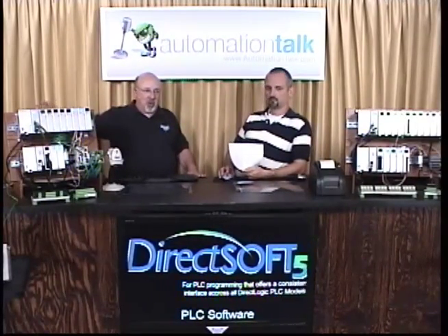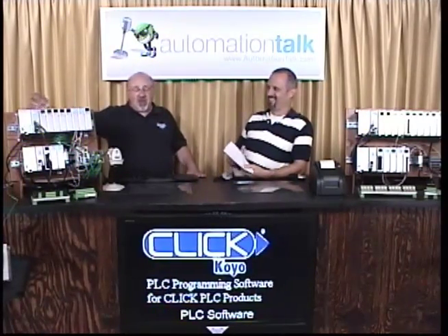We'll sit down. I just know that after the show, we always have some customers who are asking, I like that example, or I want to play with that example, or I want to see that example. But I should mention real quick, if you want to play with the example of using a GS drive to produce heat through light bulbs, it's not really a good application because a light bulb, when it's cold, has a very low resistance. So I have to tether these light bulbs a little bit to get the filaments warm, so they don't trip the drive out on overcurrent. So just a warning. It gives you good practice at playing with all the equipment and finding out the ins and outs. Kind of a cool effect watching the filaments flicker at the low frequency.